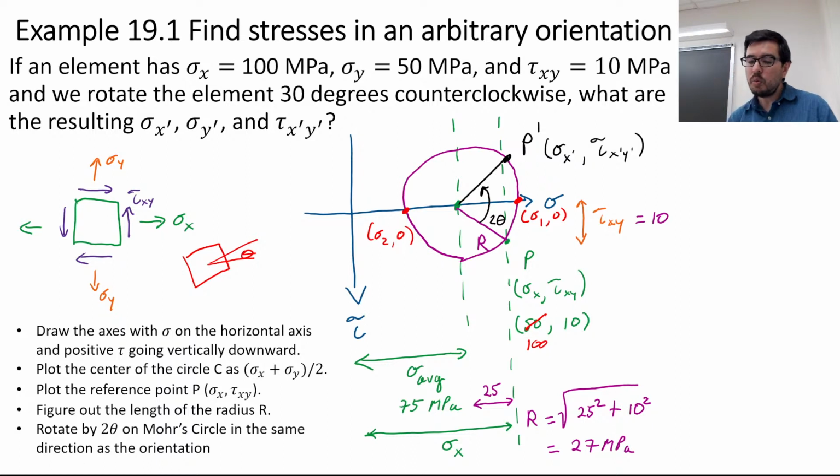Okay? So when you do the Mohr circle, what you'll see is that you can easily figure out where the principal stresses are, and you can easily figure out where the maximum in-plane shear stress is, because you've drawn this Mohr circle. And what's also neat is that you can, without too much difficulty, figure out how much you have to rotate to get to these different states. So this is where you start. This is like your initial state.